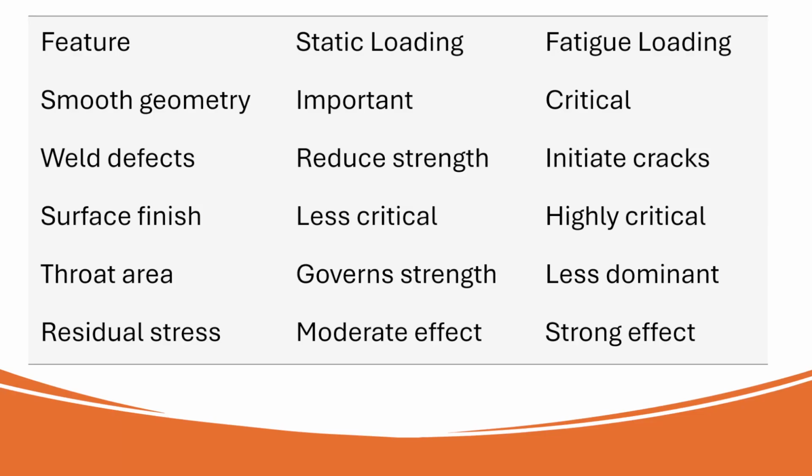So, some of the key points: smooth geometry improves static loading performance and is also critical for fatigue loading. Weld defects reduce the strength in static loading and particularly initiate cracks. Surface finish is less critical for static loading and highly critical for fatigue loading.